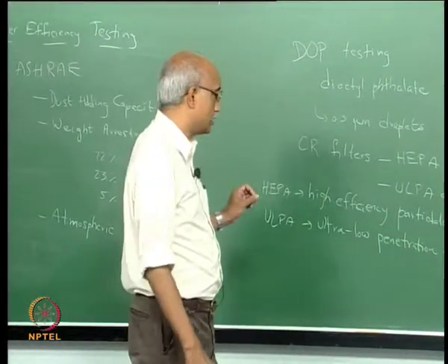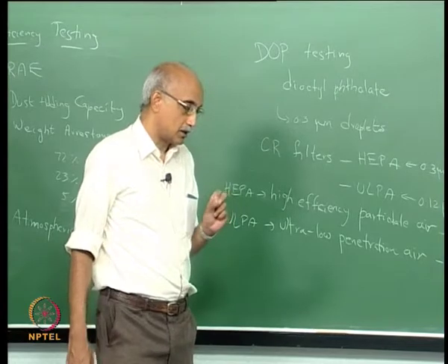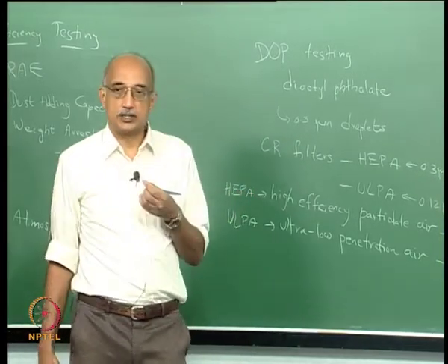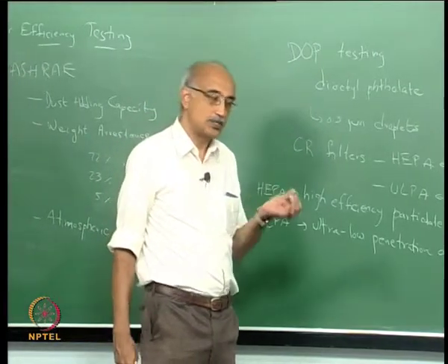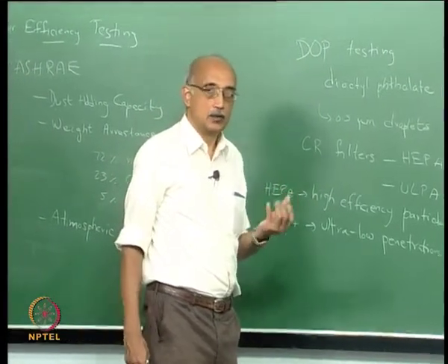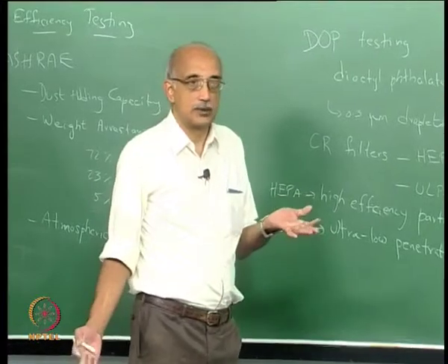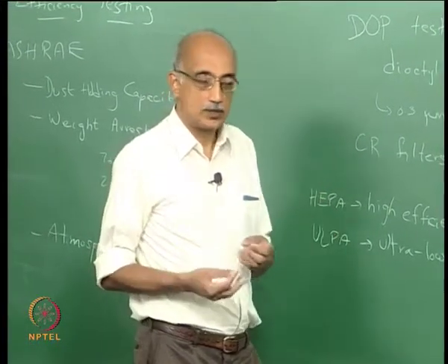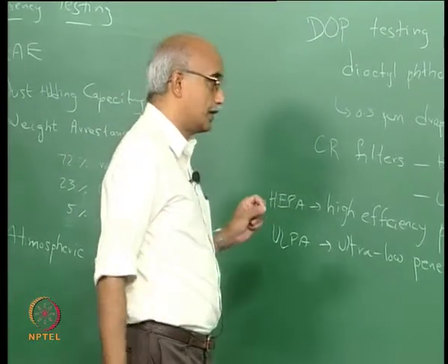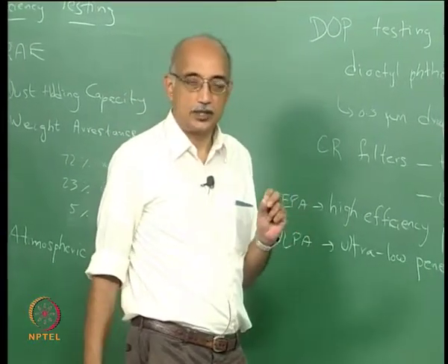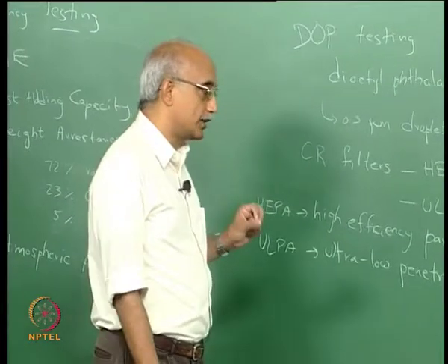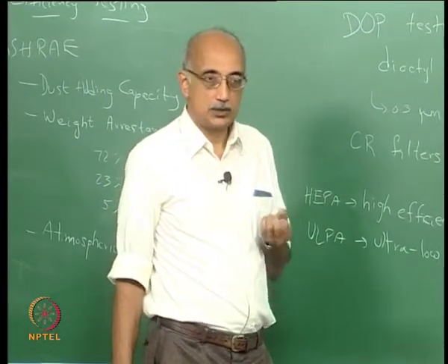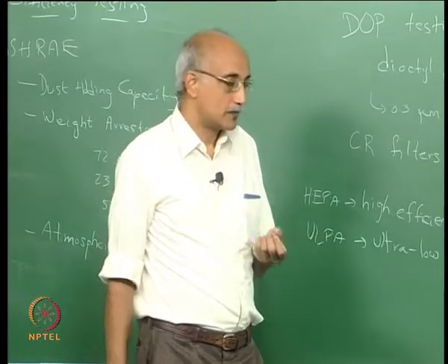Now, when we talk about filtration in a clean room, we are mainly talking about filtration of gases, and as I mentioned earlier, gases are filtered using less complicated filters than liquids because the demands are less. Liquids are much more difficult to handle. I mean, for example, fibers won't even work because fibers will simply either dissolve or swell in liquids. So, a fibrous filter really is only suitable for filtering of gases. When you talk about filtering of liquids, the only resort you have is to use membrane type filters.